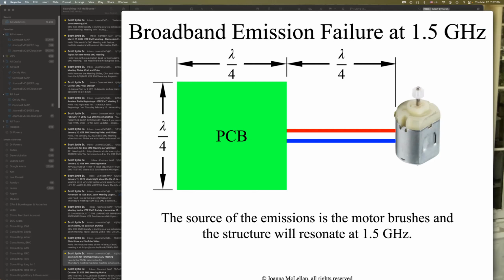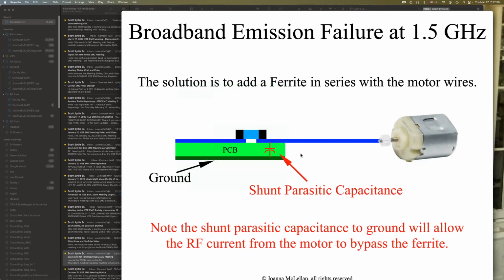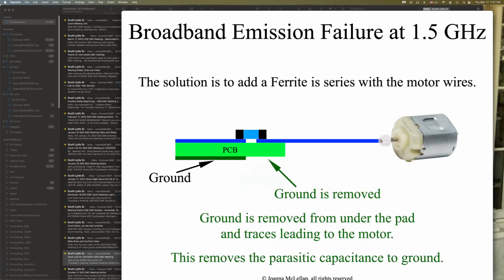I'm surprised they hadn't noticed that was a problem before. How did this problem sneak up on them? Had they just adjusted the PCB size, or was it a new model design, or what happened here? No, I just put a couple of ferrites in it. Okay, I understand. I mean, production was supposed to happen 2 months ago. We can't get this thing fixed. Here's the new artwork. Build it, test it, ship it, get it out the door. So it was a new design. That's why they hadn't noticed the problem before they put it in production. Got it.